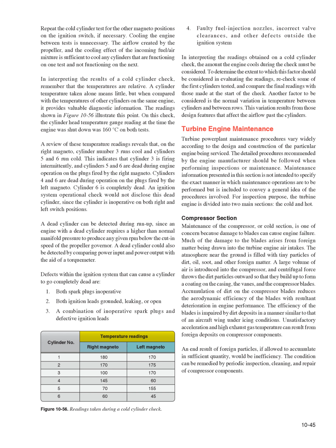Turbine engine maintenance. Turbine powerplant maintenance procedures vary widely according to the design and construction of the particular engine being serviced. The detailed procedures recommended by the engine manufacturer should be followed when performing inspections or maintenance. Maintenance information presented in this section is not intended to specify the exact manner in which maintenance operations are to be performed, but is included to convey a general idea of the procedures involved. For inspection purposes, the turbine engine is divided into two main sections, the cold and hot.